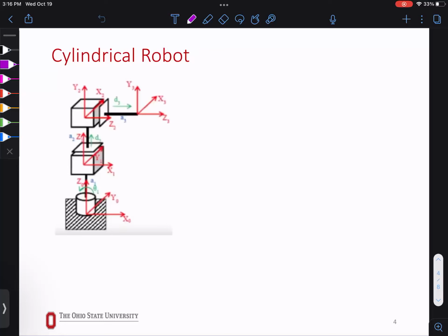So X, Y, Z axes, and then Z, Y, and X, Y. We look at it in 2D planes, derive those equations, and solve them. That way it's more intuitive, and easier, because you don't have to figure out which way it moves. When you go to those planes, you can literally see which joints move in which plane, which is very powerful.